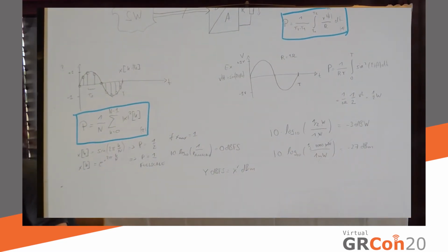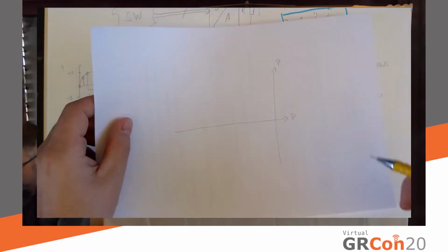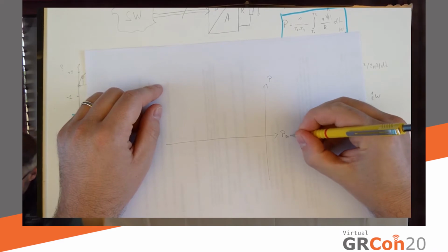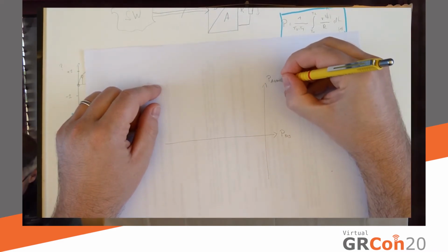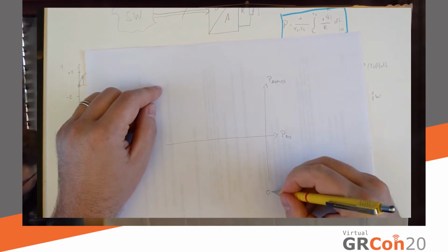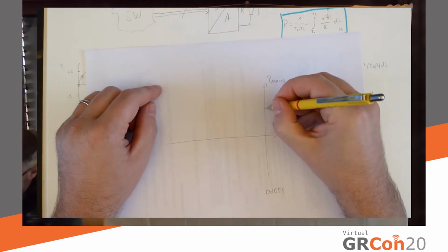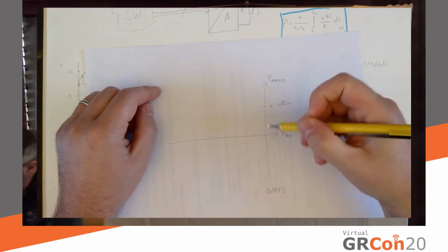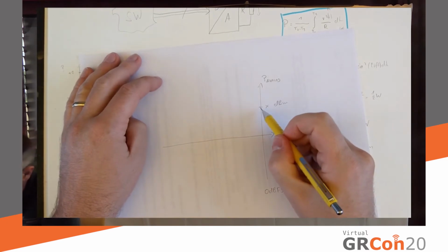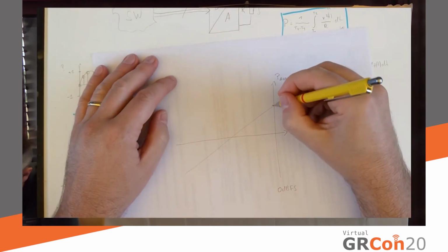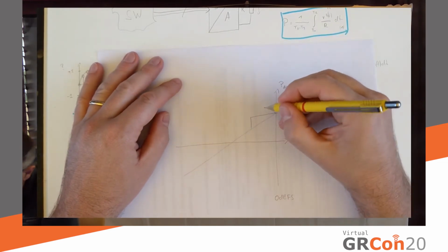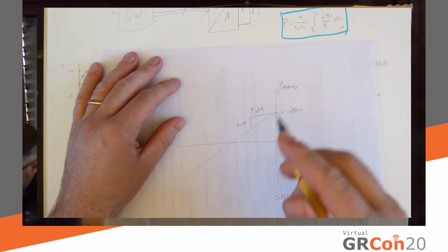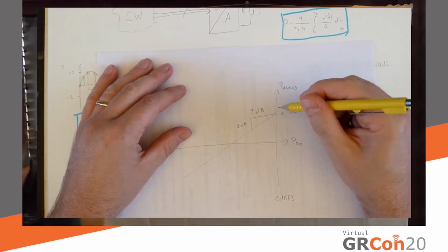I can, in fact, simplify this a little bit. I'm going to take another cheat sheet. Let's say this here is my digital power. This is my analog power. This here is 0 dBFS, so this is also a bound. And let's say this is x dBm. So if I'm at 0 dBFS and I have x dBm, my simplification will be that the response looks like this, where this curve has a unit gradient, meaning I go 1 dB in this direction, I also go 1 dB in this direction. Because this means that my x value is really all I need to know.